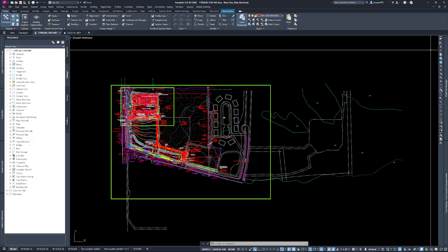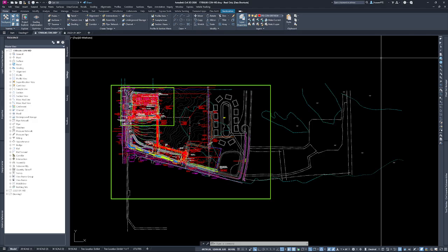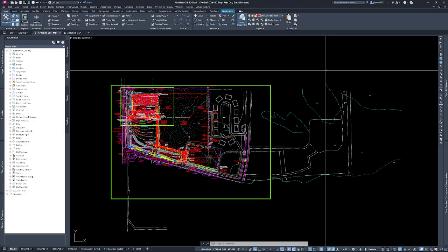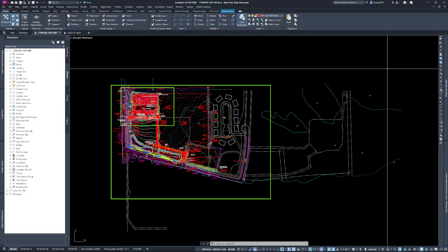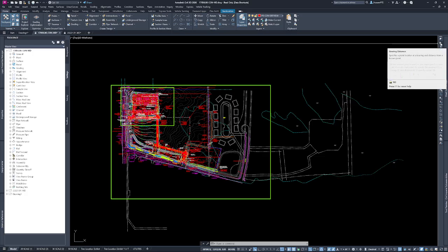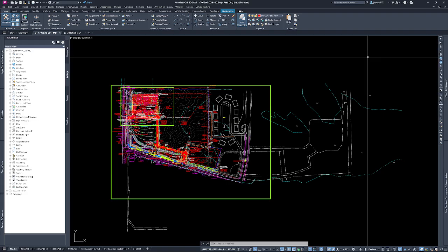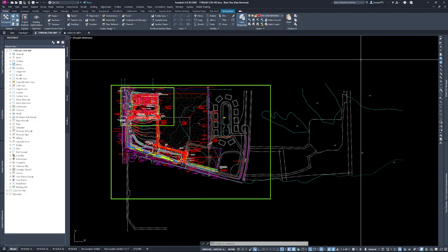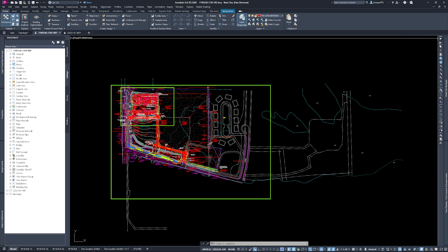Another tool that I used it for is to create, sometimes we had just a written deed, and I wanted to get the property line according to deed in. You could go in, do a polyline. There's an option here that is bearing and distance. You would just type in the bearing and distance as you go through, and it would put it all in. If you didn't want to use a parcel or one of those tools, if you just wanted a dumb polyline type of thing. So transparent tools, those were the two that I used the most.